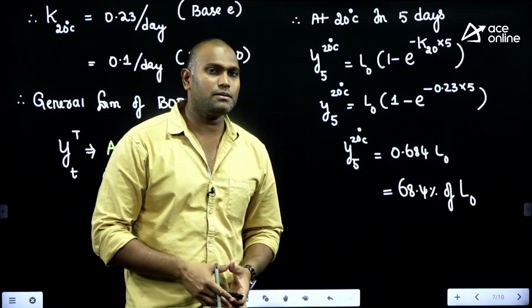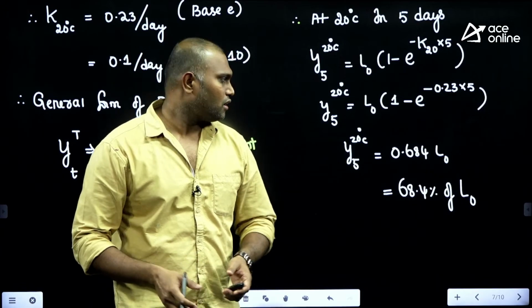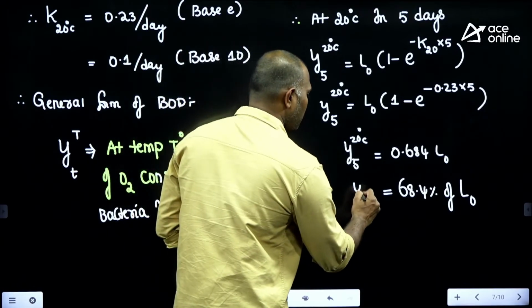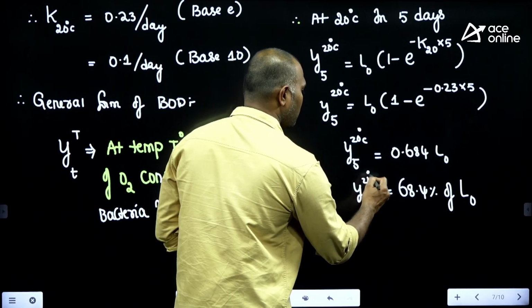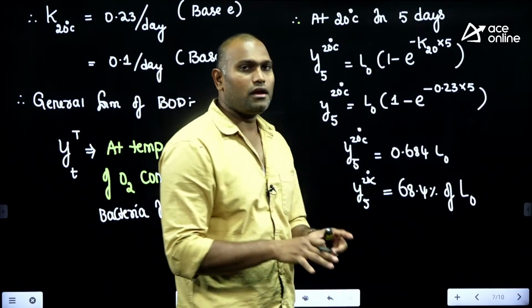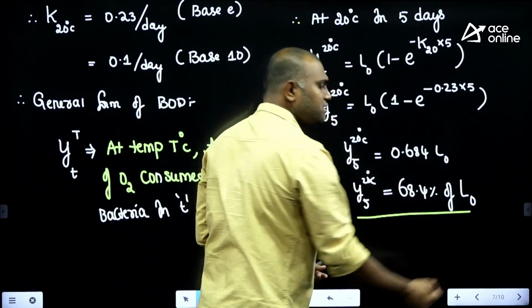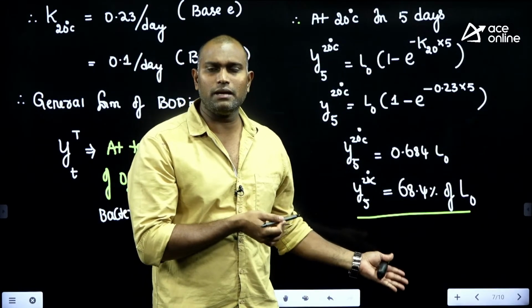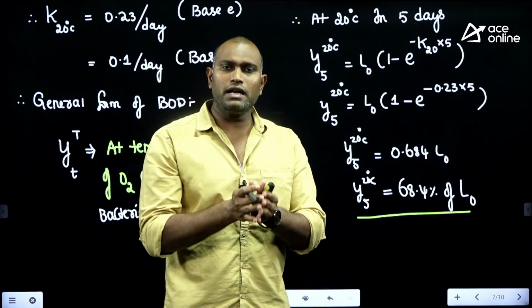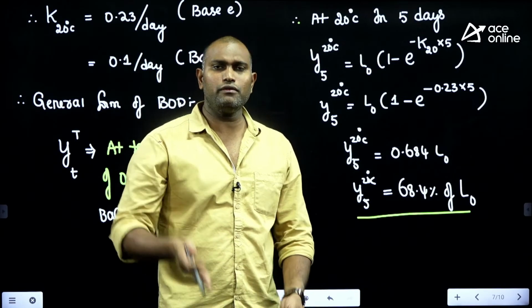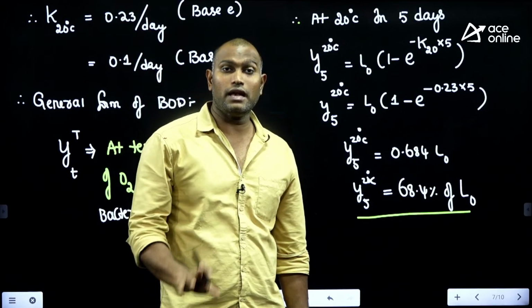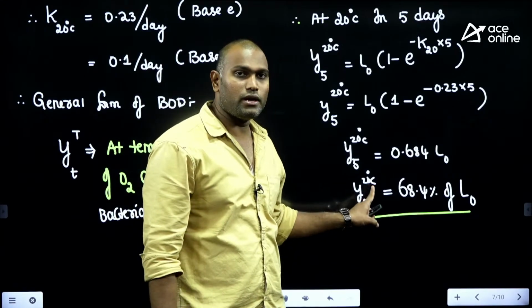So I'm not going to discuss the 5-day BOD test over here. My point is about the BOD expression. I want to explain that, which gives the entire criteria. Now, why we do the 5-day BOD test is that around 70% of the organic matter is depleted here itself. Then why wait for 20 days or 30 days? So in the lab, we conduct the 5-day BOD test.